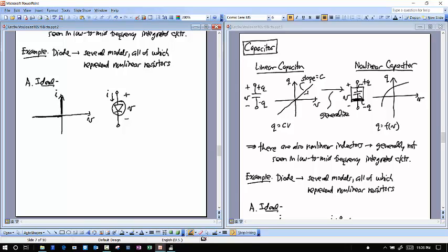But the transfer function for this ideal diode then looks like this. Okay, so it's either zero current flowing for any voltage below a certain threshold. Well, if it's ideal, the threshold will be 0 volts. And then as soon as you get to 0 volts, you pass that threshold, suddenly your current goes to infinity. And that is an ideal diode right there. And so, of course, there are no such things as ideal diodes. And so if you want to get closer to reality, you can define what's called a constant voltage diode.